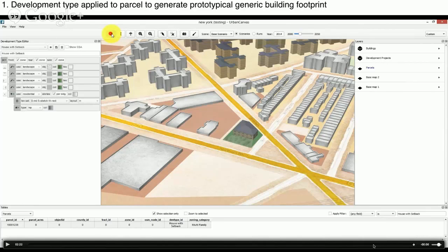So that comes back to the automatic parcel subdivision feature we were showing earlier. These things all go hand in hand. Once you have the street network, you can use that to divide the ground surface into blocks, and then the blocks into parcels with the automatic parcel subdivision we were showing earlier. And then you'll have enough information to generate frontage using some rule like the longest unshared edge will be the front. So you'll have to do a lot less manual work to do this.